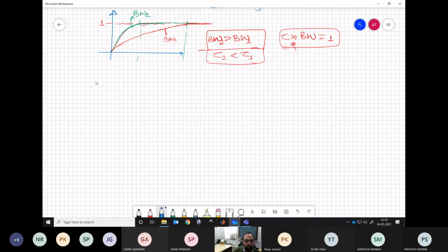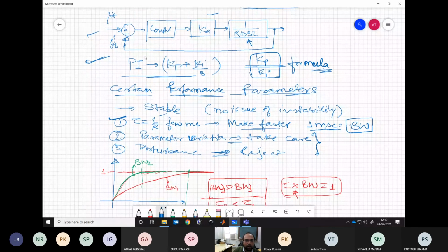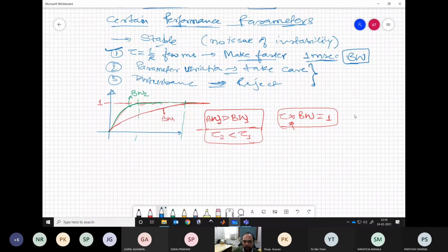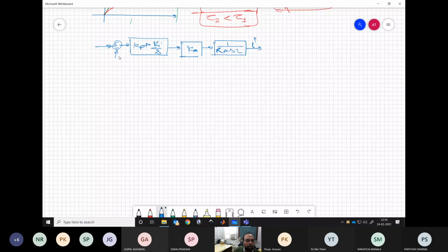So we have this block diagram. I will just go back to that. So if you note, there are 3 parts. Maybe for clarity, I will write it again. The control loop along with the Kp and Ki, what we have given for the PI controller. Then we have the power converter, and then we have our machine. So this is generating our reference current.